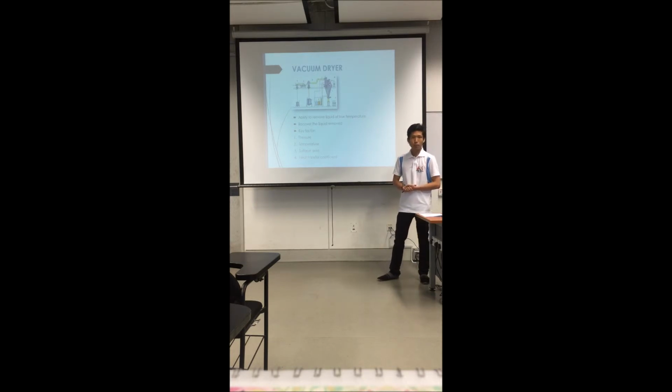Vacuum drying is a batch operation. This gives it the advantage of being extremely flexible and multi-purpose. A vacuum dryer can handle many materials, from thick slurries to solids, which in our case is the fruits and the bananas. Vacuum drying cycle times depend, besides product characteristics, on several key factors, which are the pressure, temperature, surface area, and also the heat transfer coefficient.